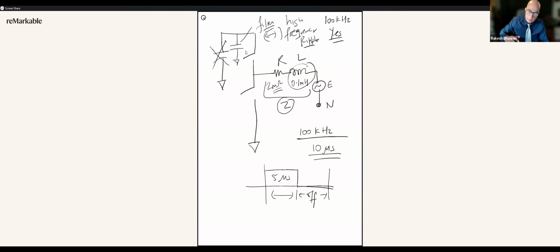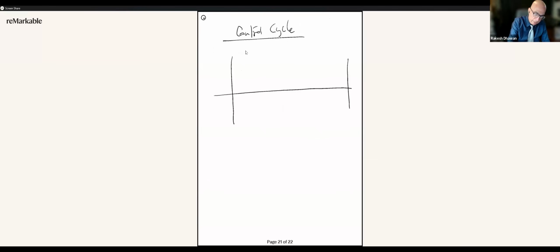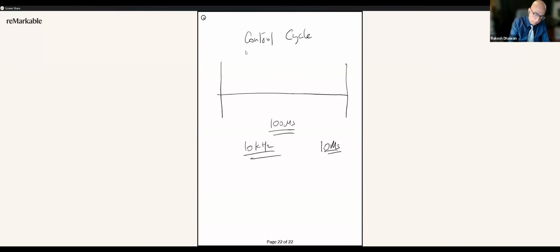When you go to lower frequency and your impedance is low, you can have more ripple in the motor, and you're going to have more torque ripple in the motor, okay? So we can have an advantage where, if you're using a slower processor, you have a 10 kilohertz control cycle and a 100 kilohertz switching cycle. But if you can maintain both at 10 microseconds, it is wonderful.